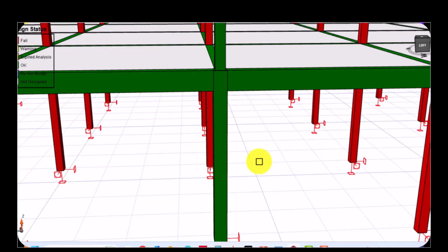Buckling is not a strength failure. Let's keep that in mind also. It's part of an instability failure. So let's take wind load pushing on the transverse axis, and the column is not strong enough to resist that. Buckling will surely occur.